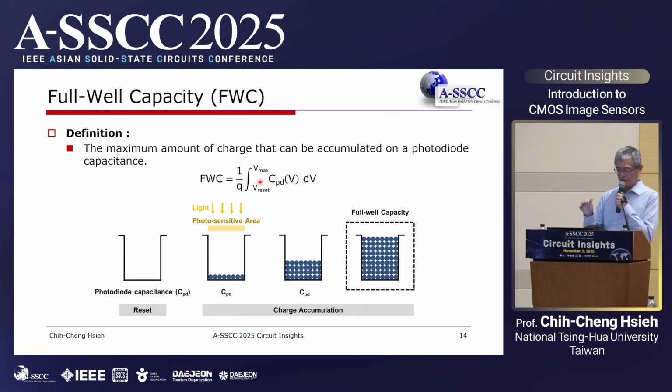So basically, you need to carefully arrange your bias point, from your very front end through all the signal paths, and propagate and interface each block at the correct biasing voltage to maximize the available swing at the sensor node.